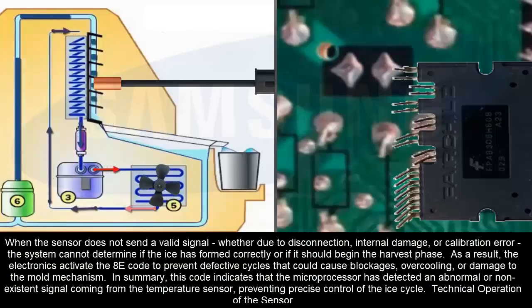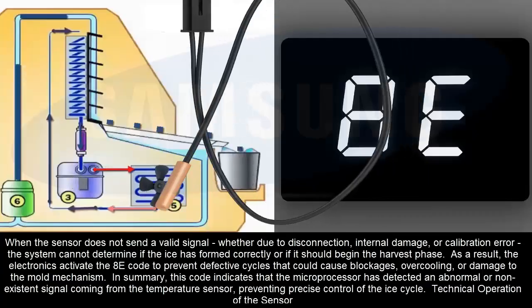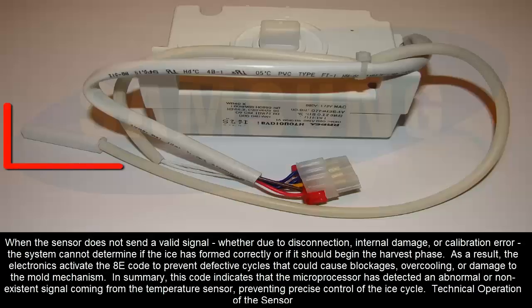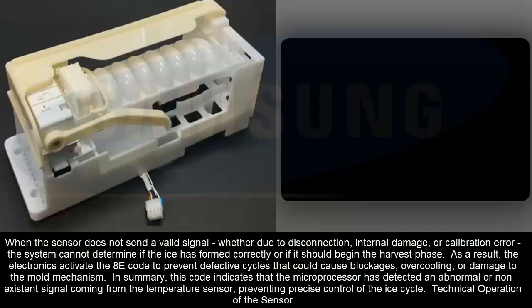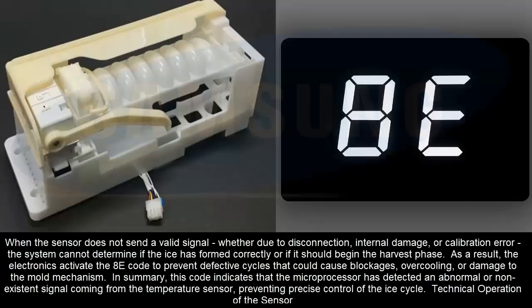When the sensor does not send a valid signal, whether due to disconnection, internal damage, or calibration error, the system cannot determine if the ice is formed correctly or if it should begin the harvest phase. As a result, the electronics activate the 8E code to prevent defective cycles that could cause blockages, overcooling, or damage to the mold mechanism. In summary, this code indicates that the microprocessor has detected an abnormal or non-existent signal coming from the temperature sensor, preventing precise control of the ice cycle.